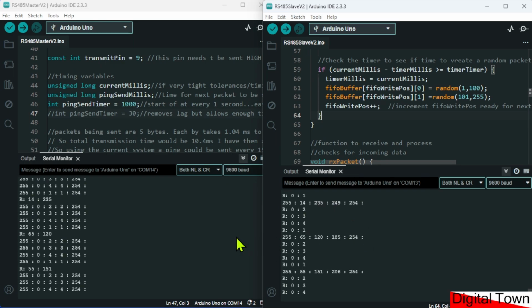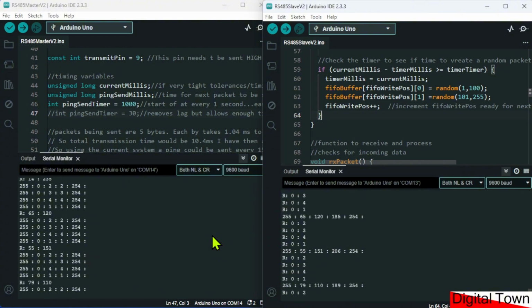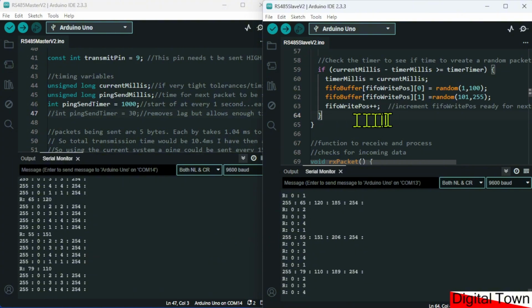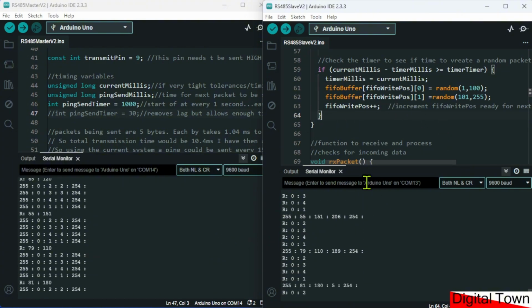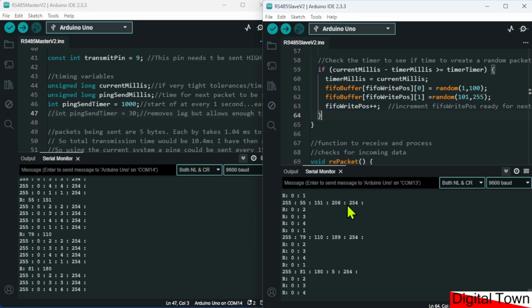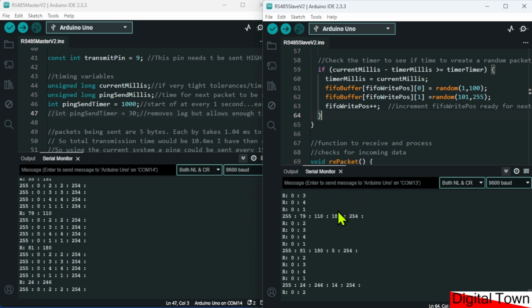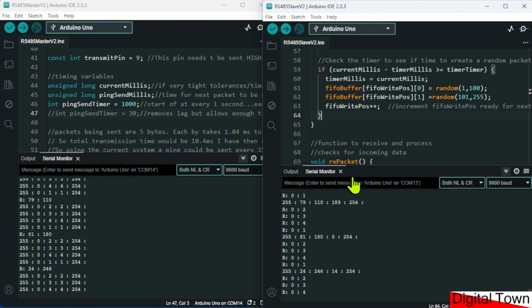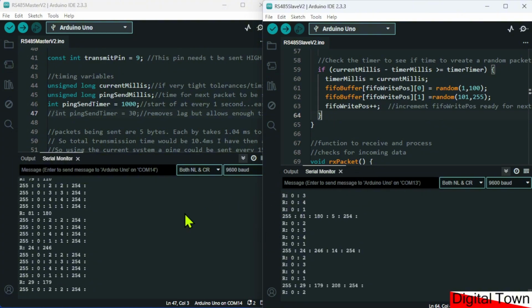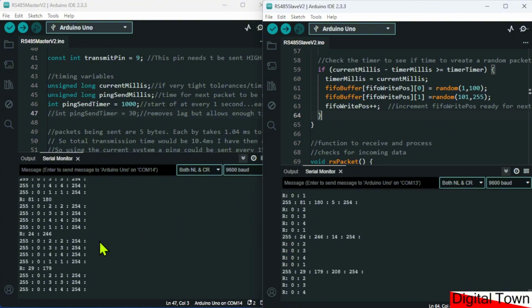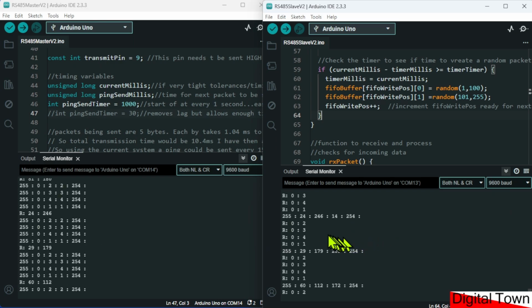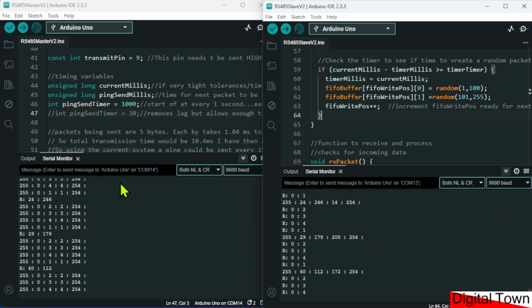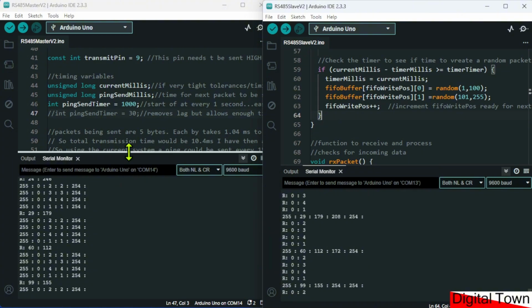Now that we're working on the RS485 bus, any data that is transmitted from the slave is available for any other board to read. So don't think of it anymore as the slave responding to the master, as in the master gets all the data. It's just a case of the master controlling the timing of the system.